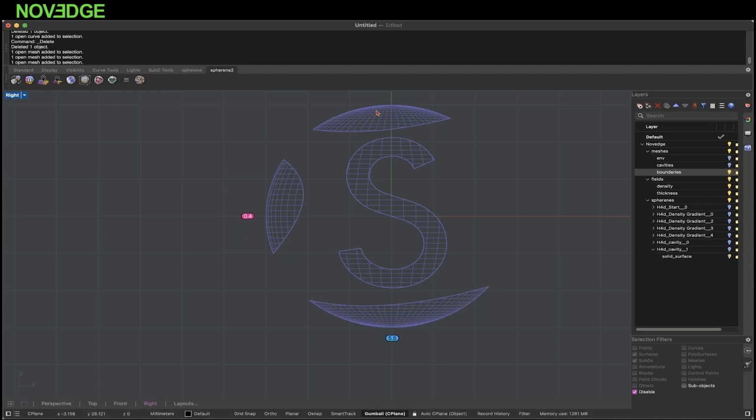Now we will make some changes. So here we have these two flags, back and front face. So let's play with them first. On the top part, I will deactivate this. On the bottom part, I will deactivate the other one. And here for this part, I will set the hull thickness to 0. So it will be 0 walls, will not show up, but it will thicken up the Spherene to 1.2 millimeters.